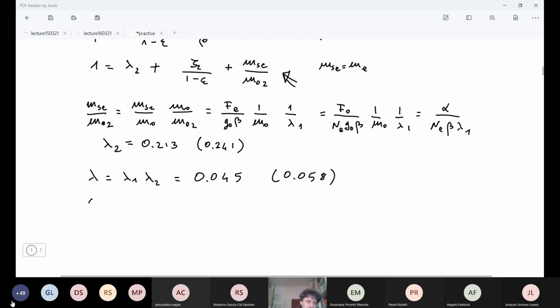AI1, of course, is 1.5 G0, and AF will be given by the mass ratio. Of course, we have the same thrust, and so the only change will be the change of mass. That will change the acceleration, and we end with operation of the first stage with 4.62 G0.